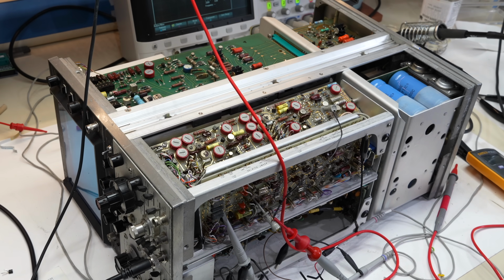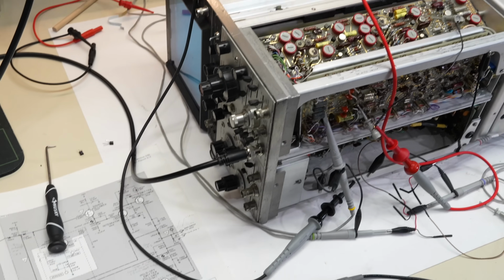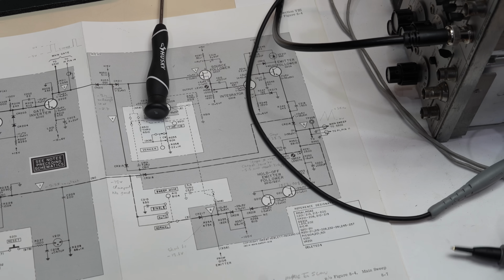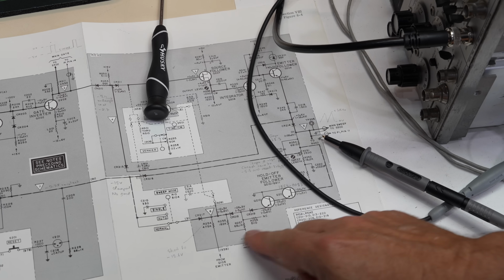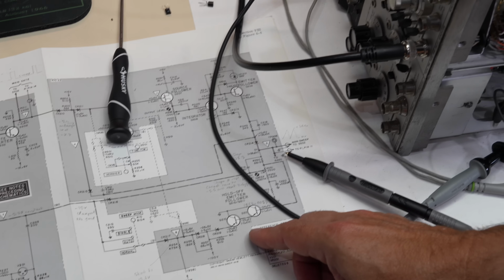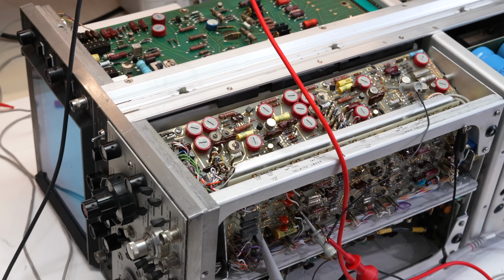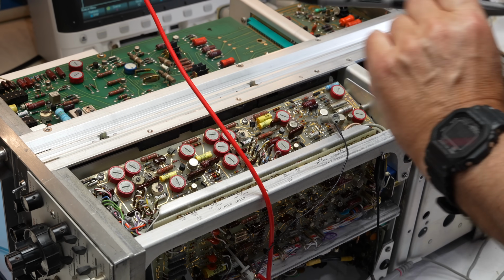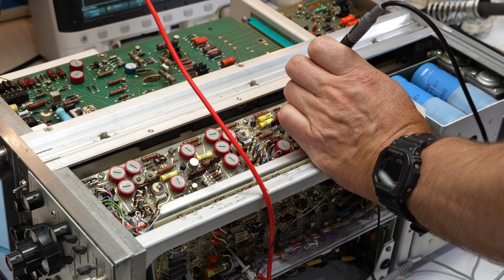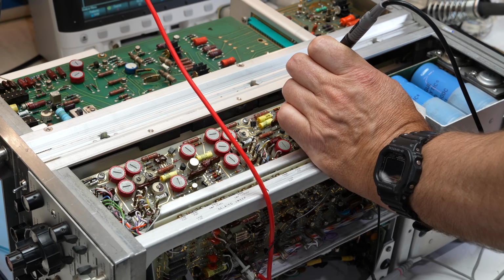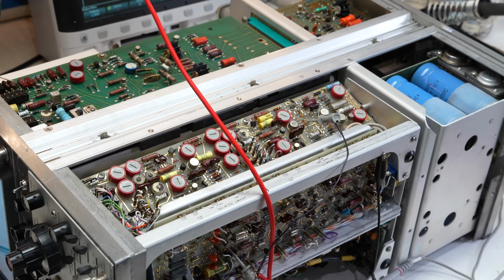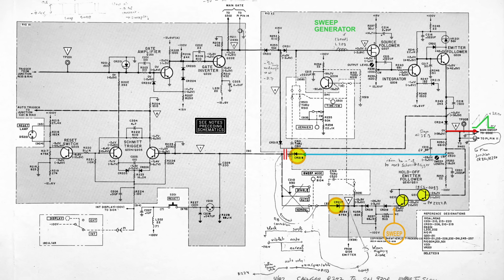Okay, I've been poking around a bit, trying to figure out what could cause our transistor here to be zapped. And when I started to measure around here, it was bizarre. It turns out I have a short from that point 8 to minus 12.6 volts. If I go here, and I go on the power supply minus 12.6 volts, direct short, 0.0 ohms.